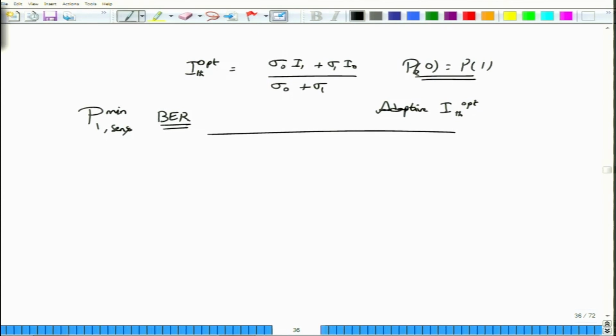and sensitivity is an important parameter of optical receivers, but the way I have defined sensitivity, I have masked a lot of complications in this definition, because the sensitivity depends on the optical preamplifier that is commonly used, it depends on the exact receive filter design, it depends on our capability to adaptively change the threshold, because if you are not including an adaptively changing threshold, then the optimum value cannot be adjusted and minimum sensitivity may not be achieved.